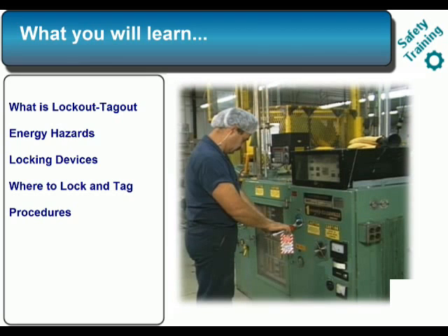At our company, only authorized and trained employees may place a lockout on any piece of equipment. Only company-provided locks and tags are to be used for our lockout, tagout procedures. The person who will be doing the work on a piece of equipment must be the one who installs the locks and tags, and after the work has been completed, only they are allowed to remove the locks and tags.